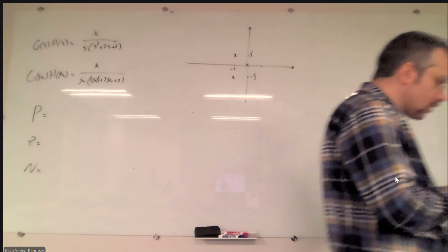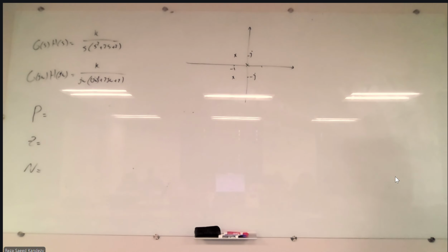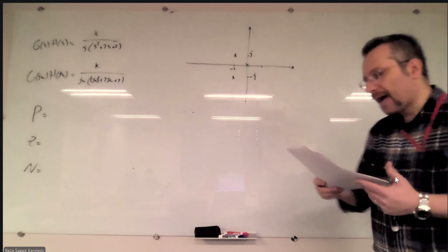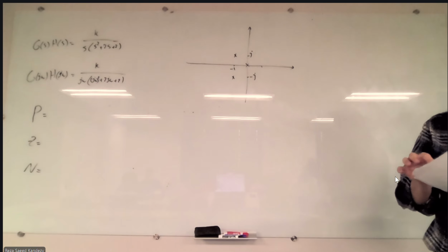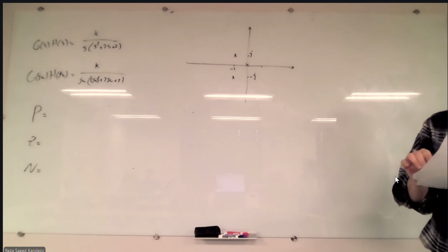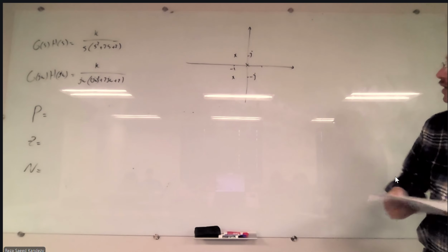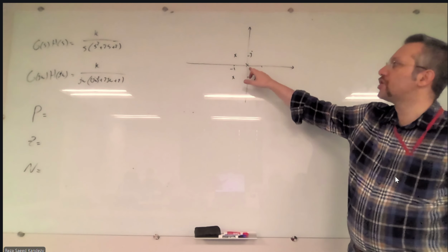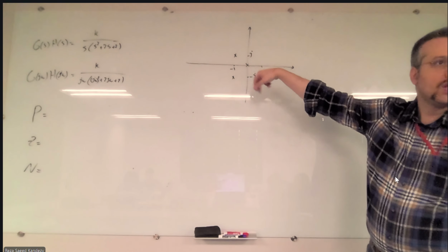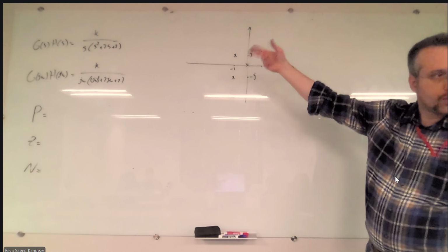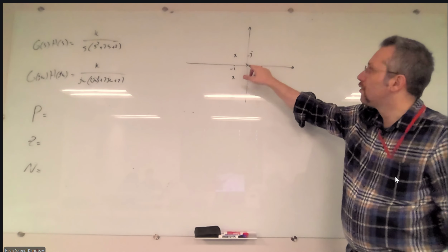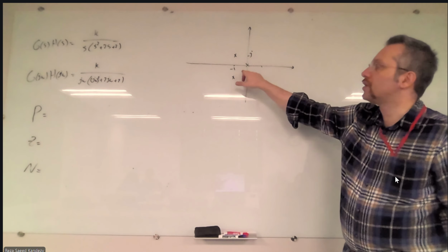So, before we consider how many poles we have in our S domain, in the right hand side, because we have a pole in the origin on the j omega axis, we have to turn around that pole either from the right hand side or the left hand side.